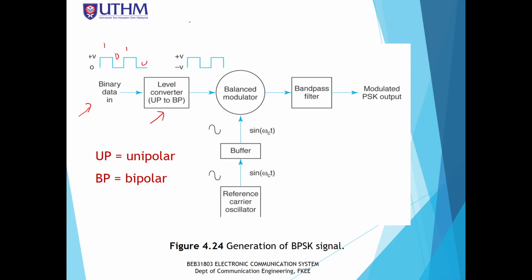Bipolar means we have positive and negative voltage polarity. Then it goes into the balanced modulator, which will multiply it with another signal, which is a sine wave.